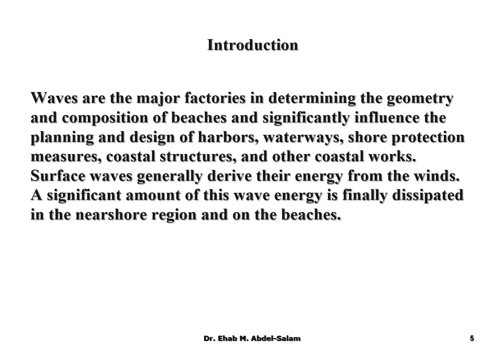Introduction. Waves are the major factors in determining the geometry and composition of beaches and significantly influence the planning and the design of harbors, waterways, shore protection measures, coastal structures, and other coastal works. Surface waves generally derive their energy from the winds. Very important: a significant amount of this wave energy is finally dissipated in the near shore region and on the beaches.